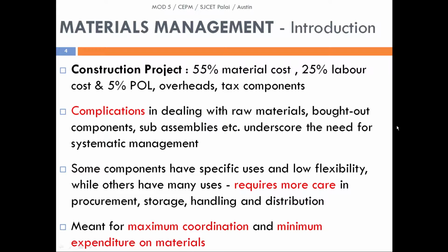Then we have to see why material management is important. What is the necessity of material management? In a construction project, we could see that material cost alone sums up to 55% of the total cost of the construction project, and 25% labor cost, 5% POL cost, then other overhead or indirect cost, tax components, likewise.